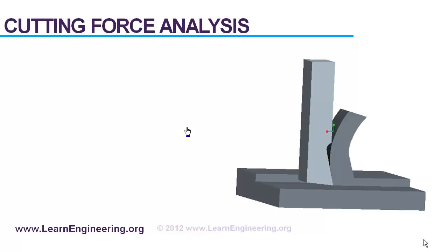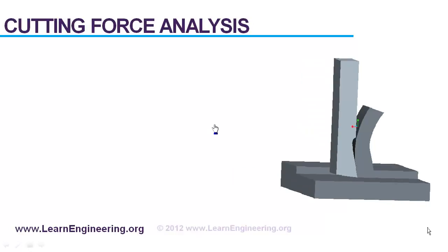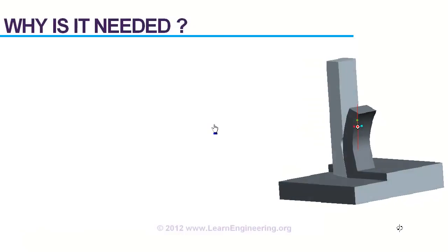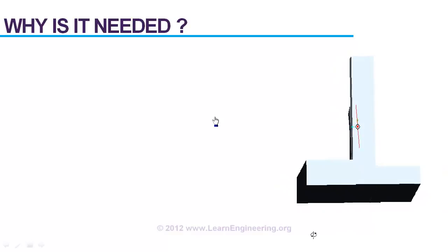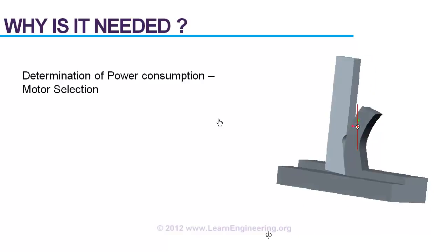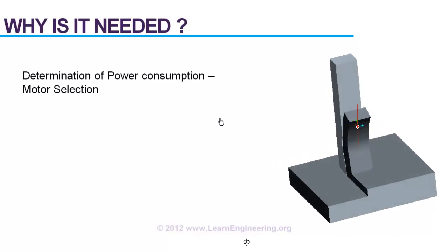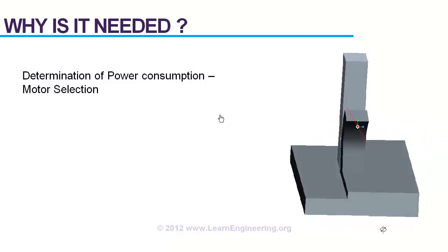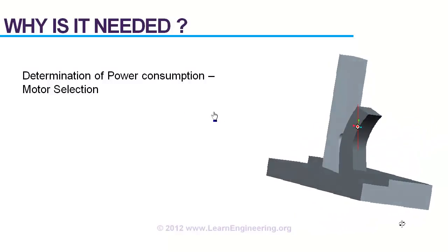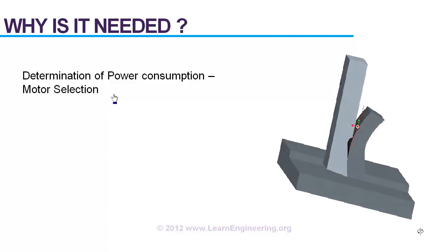In today's video, we will learn how to predict forces acting on a cutting tool while it's undergoing single point orthogonal cutting. So the basic question: why is prediction of cutting force so important? Because of these reasons. First, you have to determine how much power is consumed while doing a cutting operation. And this is important because this will finally result in motor selection.